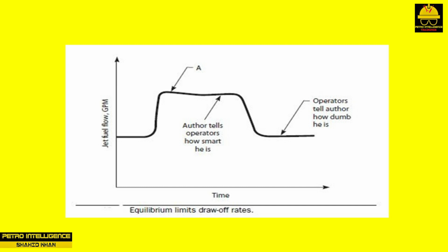What happened? The problem is equilibrium. When the pressure in the tower was raised, lighter components from the vapor were forced to dissolve in the pool of liquid in the draw-off sump. This meant that, at the new equilibrium conditions, the lighter liquid would boil not at 10 psi but at 14 psi.